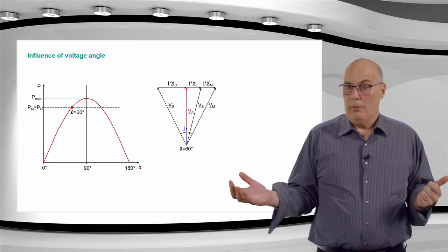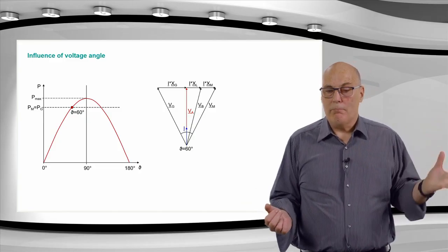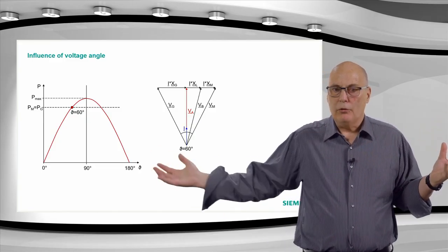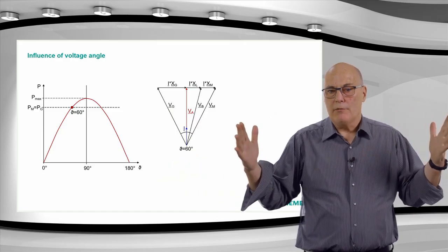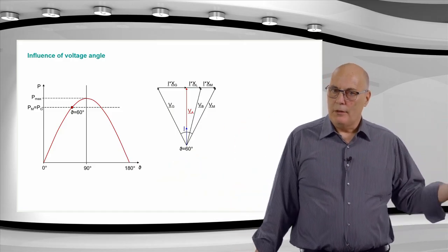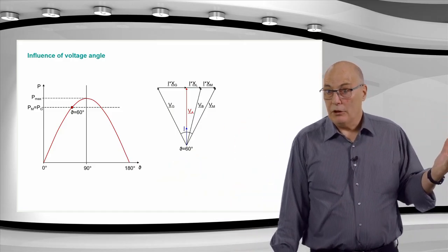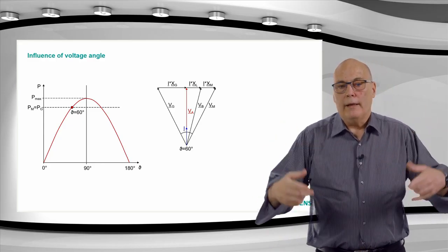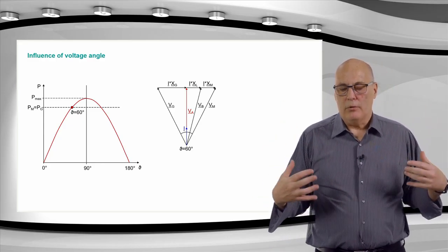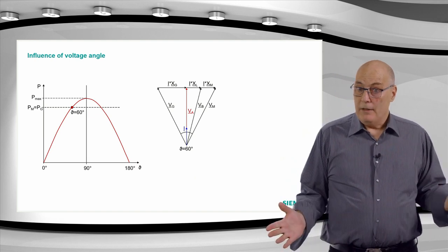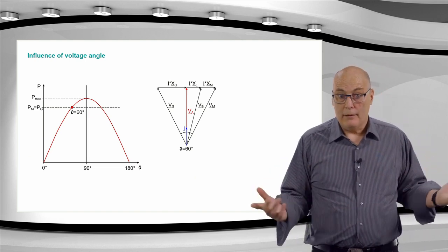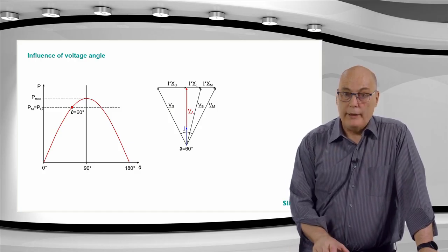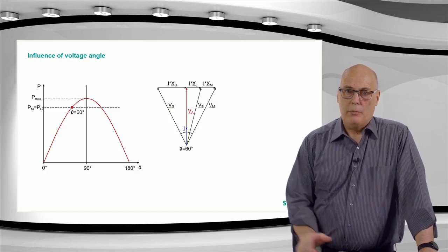And then you have a problem, because then there is real energy at the generator side which does not reach the motor side, because it cannot be transferred. That means the generator needs to store that energy. Generators can store energy a little bit. How do they do that? They increase their rotational speed. They store it as rotational energy. The generator will accelerate, and we have then a problem. The frequency will go up, and we get then already a power swing condition.